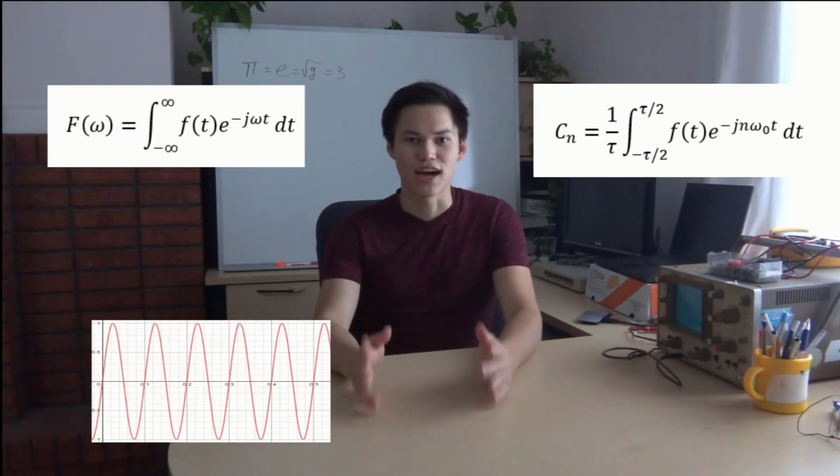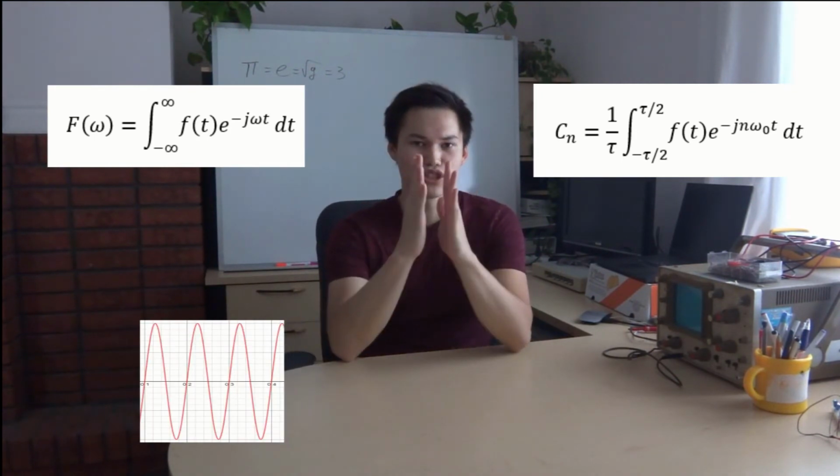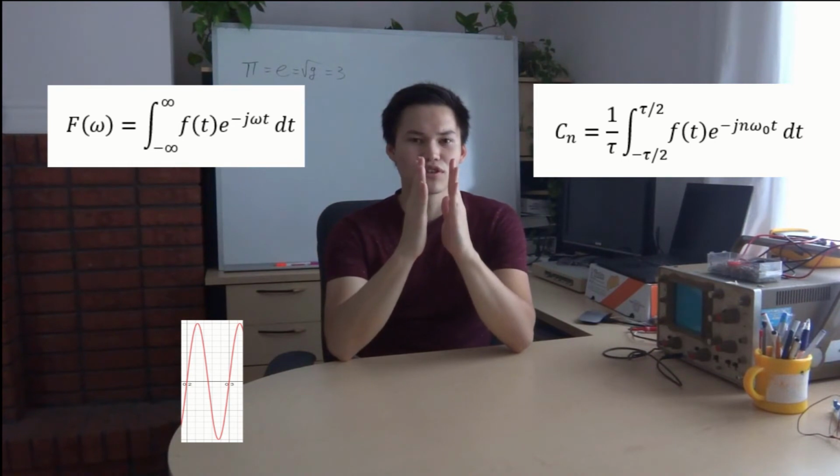Let's say you have a 10 Hz sine wave, and you're only looking at a narrow portion of it. So you're not certain if it's actually 10 Hz or maybe 15 Hz. And that results in a spreading out of your frequency plot. You're just not confident that it is actually 10 Hz. But if you extend the range of your Fourier transform, then you can be more and more confident that it is actually 10 Hz because you have more and more information. See, with an average, you don't get that because the amplitude of your frequency output is constant, and you don't get those high spikes the larger your time interval, which means you don't know how confident you really are.